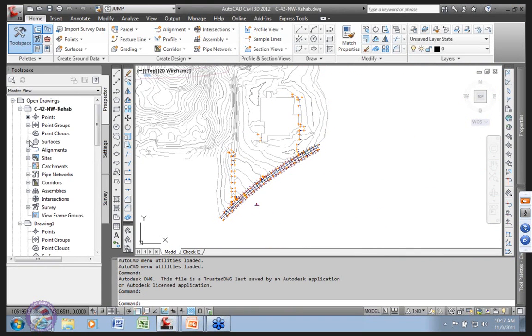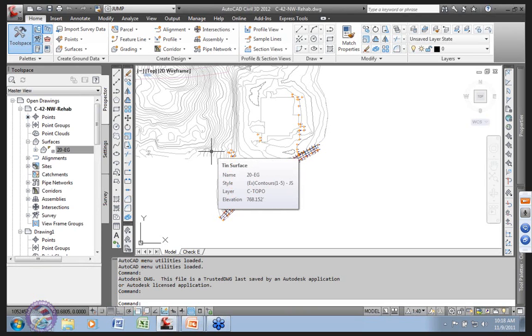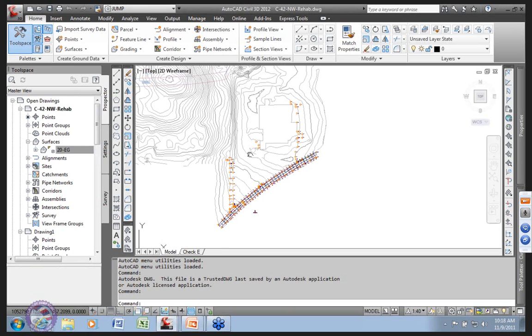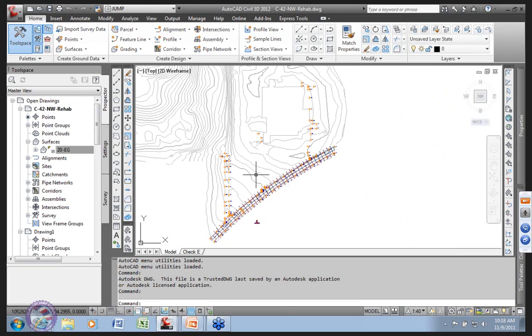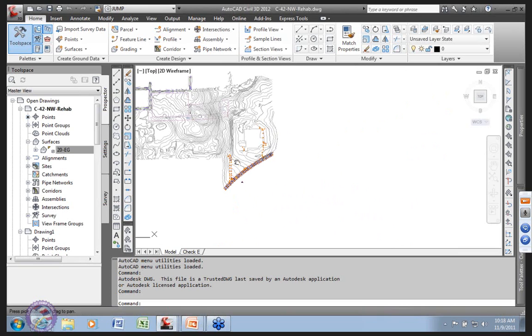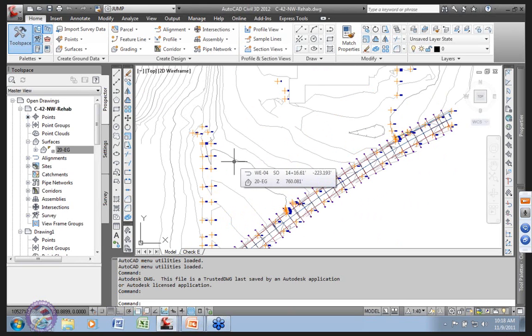We also have in our drawing a surface, which is, I can see, a data reference surface built by the survey guys. It actually, if I went and opened the drawing, you would find that it's actually hooked to an XML file. So pretty hard to edit. Okay, it produces the existing surface that they've certified, said, hey, this is what we found in the real world. And we also took some of their points. They came from somewhere, and we'll talk about how we got just those points looking just this way